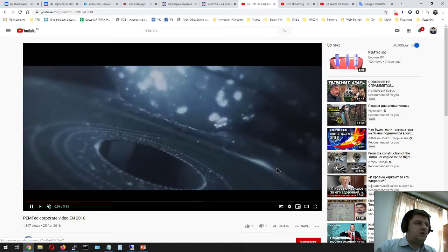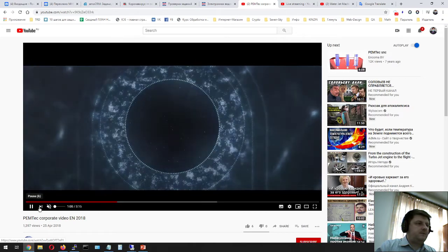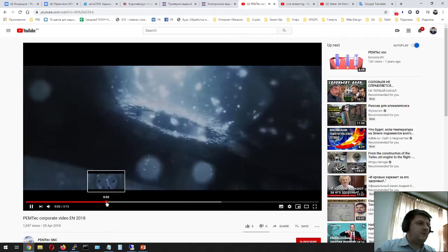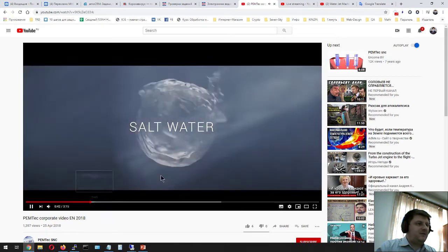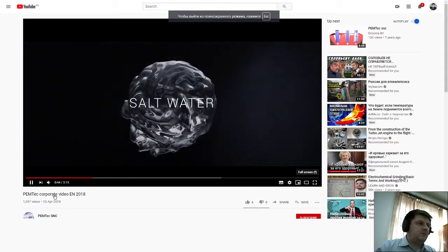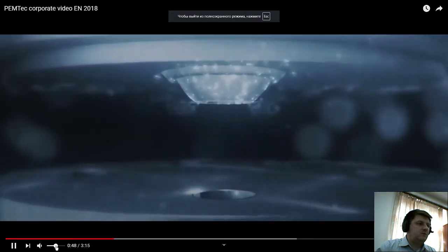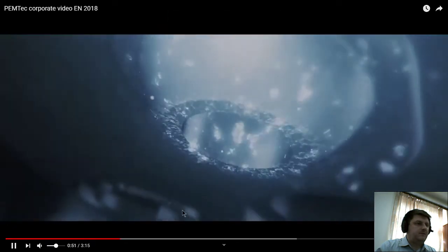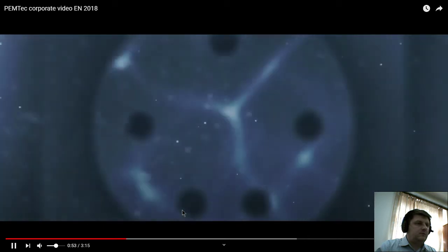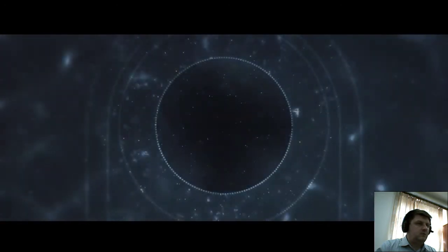So you can see the workpieces with a metal shape, material, inductive electrolyte, salt water. It dissolves the ionized material anodically in the machining gap between electrode and workpiece. The electrode shape is projected inversely onto the metal. Contact-free and without thermal or mechanical influences, workpieces with an imaging accuracy in the lower micrometer range and a surface quality of up to 0.03 micrometers are produced in high repeatability.